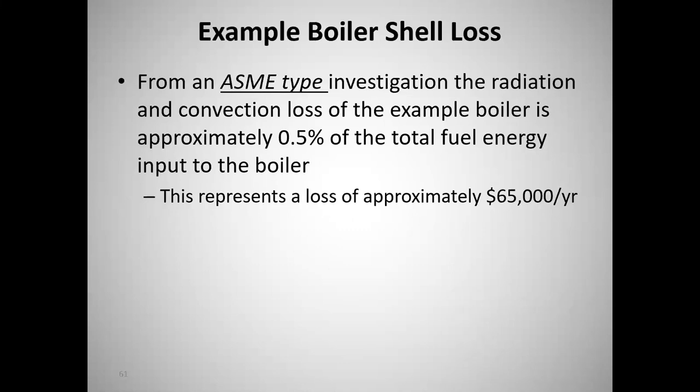So it just gives you some kind of an idea of the magnitude on a boiler, 100,000 pounds an hour. That's about what Tennessee Tech runs, something like that. We've got a 2,000 horsepower, which is 68,000 pounds an hour. And when it gets cold outside, they have a couple other boilers over there, and I think they have to run more than one. So on the high side, and plus when we have the new fitness center and this new science building online, our load will probably go up to on the order of 100,000 pounds an hour. So you think about Tennessee Tech, we're heating all these buildings around here, and our shell loss over there is probably someplace between $50,000 and $100,000 a year. Now, is there anything we can do about that? Well, we're going to talk about that here in the next couple of slides.